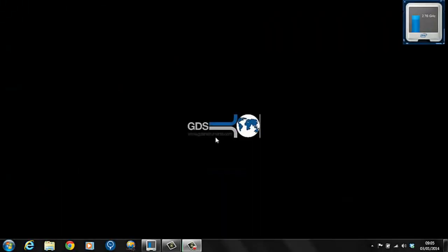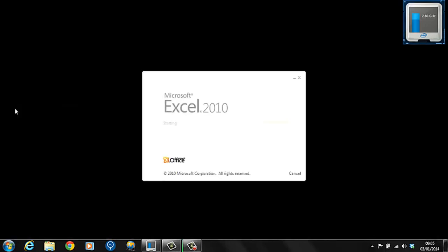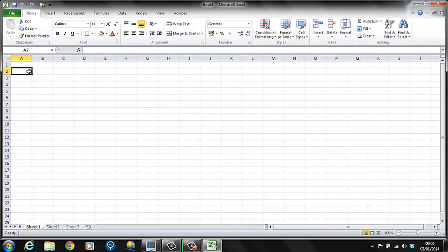We're now going to learn how to create a custom time file to be used within GDS Lab. To start, you can use two different programs, one being Microsoft Excel and the other being Notepad. The end result is to create a .csv file with your data save intervals created and stored within. We'll start by using Microsoft Excel. Do this by entering all the values only within column A. I'm going to use a data save interval of every 5 seconds.